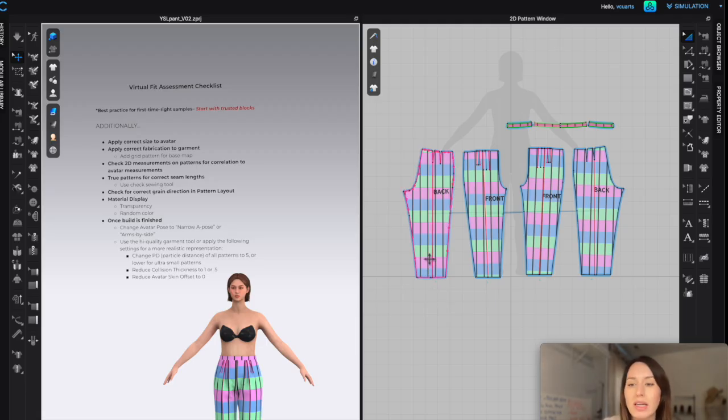When your vertices are further apart, so a higher number, default is 20, let's say, yeah? So 20 millimeters apart from each other, these vertices of your 3D mesh are. That's creating a pretty chunky, low quality mesh. When you lower that number to 5 millimeters apart, then you're creating a denser mesh, and it becomes a higher quality object, and then shows you a more realistic representation of it.